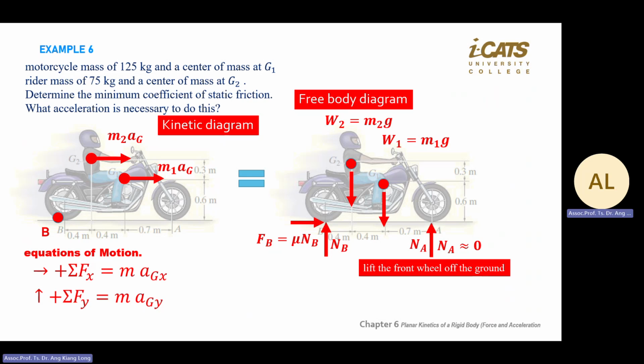And then the second equation, F equal to ma in the y direction. So you have 4 forces here, with Na equal to 0. Go up positive. So you have positive Nb, positive Na, but Na is 0. And then W1, W2, negative, going down, equal to may. Here you look at the diagram, there's no may. So this one is 0. So the second equation will give you Fy equal to 0. Then you solve the simultaneous equations.